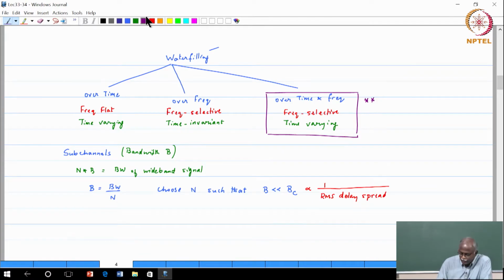Okay, so here is the other side of it, the equalizer complexity side. The equalizer complexity side says, if I have a narrow band channel, this basically means that the bandwidth is small. If I reduce the bandwidth, the impact will be seen in that the symbol period will increase, correct.